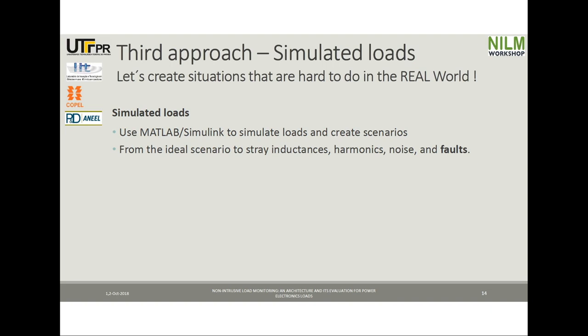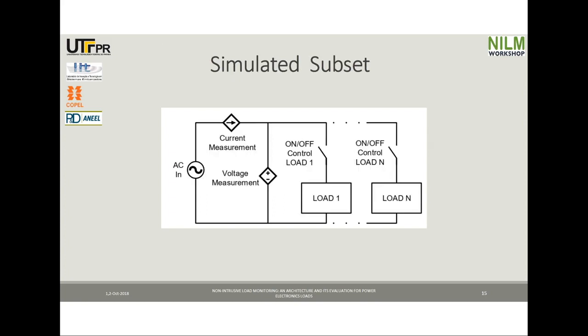And we can play a lot with the number of harmonics we have in the main signal, the inductance of the lines, the noise that we aggregate to the system, and obviously the faults. So this is the simulated environment, very similar to the other ones. So far, we are working with up to 5 simultaneous loads. We chose 5 for a practical reason. It takes a lot of time to do every simulation, so as you increase the number of loads, it takes longer.